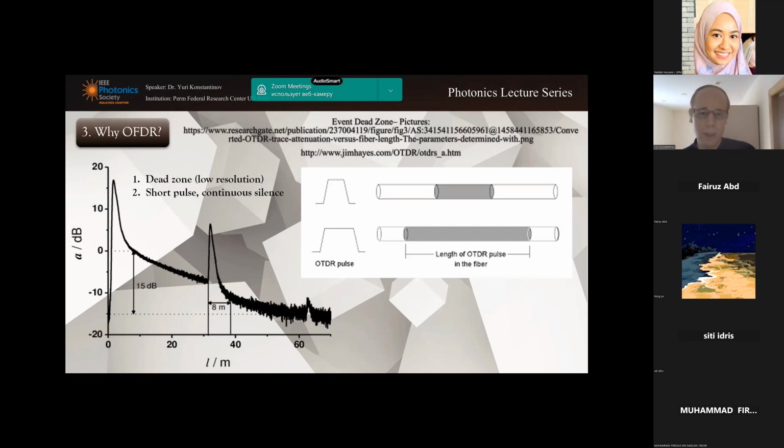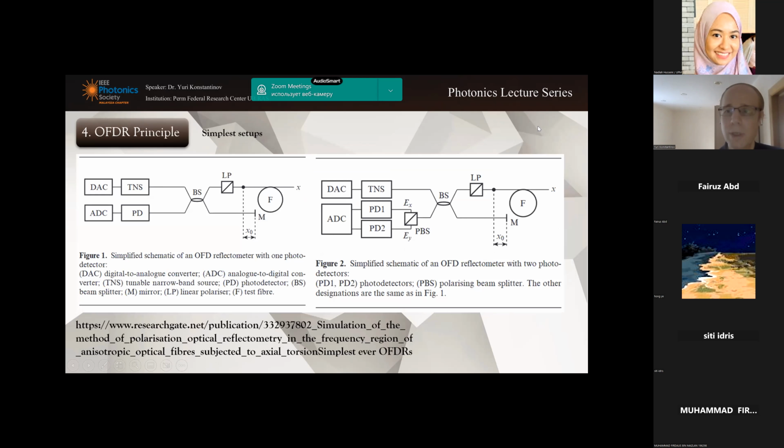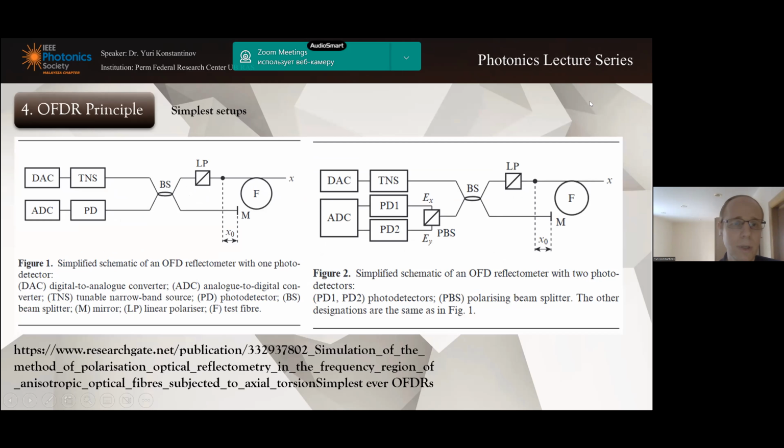Of course, in general, in the line you will not have very high power to reach high SNR and to measure fibers with high attenuation, for example erbium-doped fibers or holmium-doped fibers, and so on. So to get higher resolution, the OFDR principle is a perfect solution.